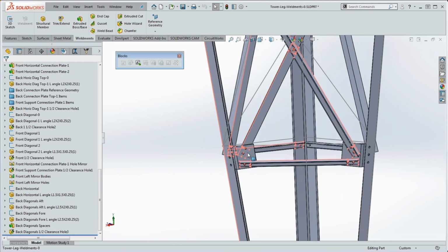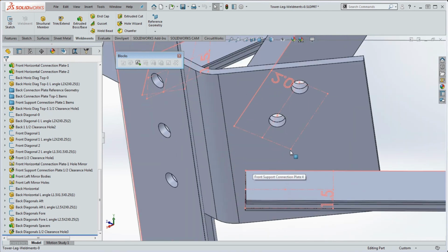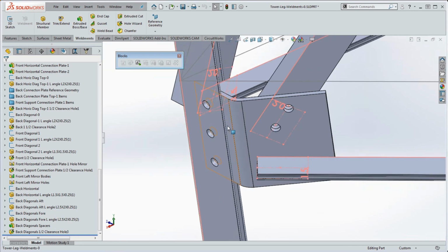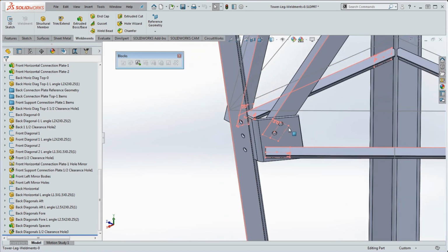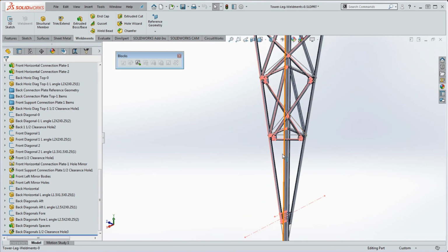Like, how do you get these connection plates put in? And some other elements in here too in order to make for a complete model. We didn't get a chance to cover that in the session, but if you desire more information on that, I'm willing to share that with you too. Essentially, these connection plates are nothing more than surface models or thin extrudes consisting of a line back here and a line over here connected by a fillet. Then this line, which will define the back of the connection plate, is perpendicular to a plane that runs right down the middle of our model.